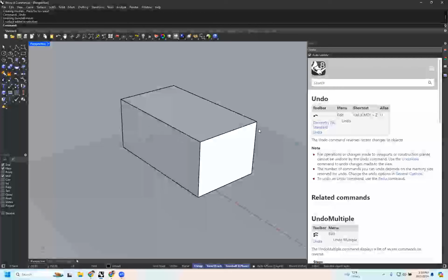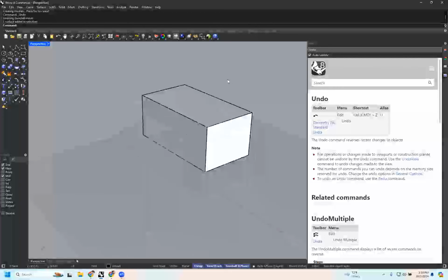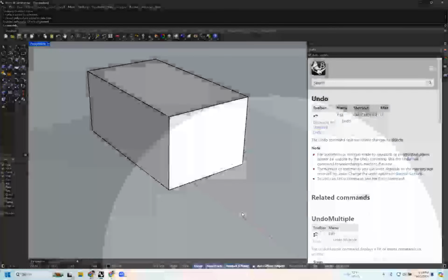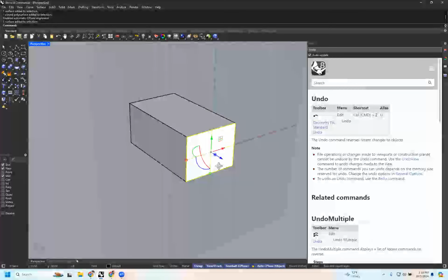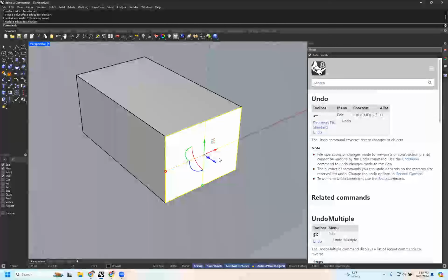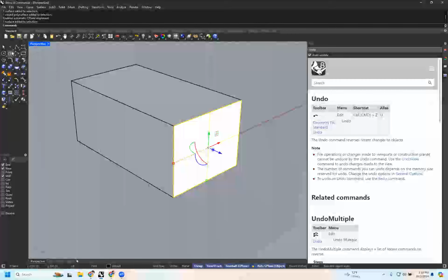Couple more just little things here. Like I said, it's kind of fun to draw in Rhino. They have this auto plane option that we've now added down here. So if I did sub select and made it, it puts the plane right onto our surface.